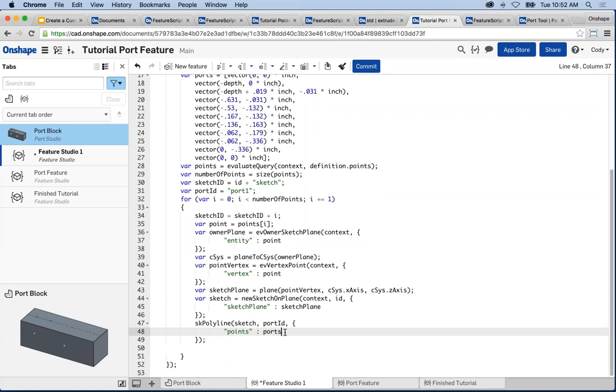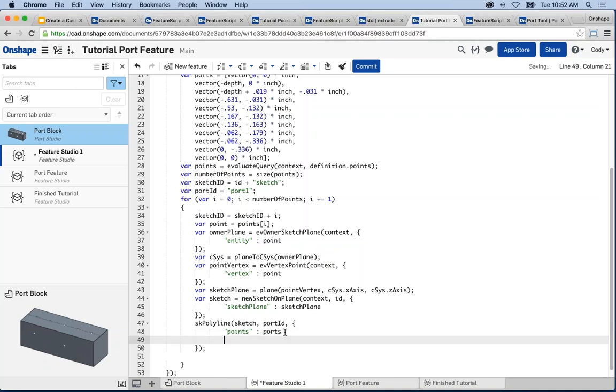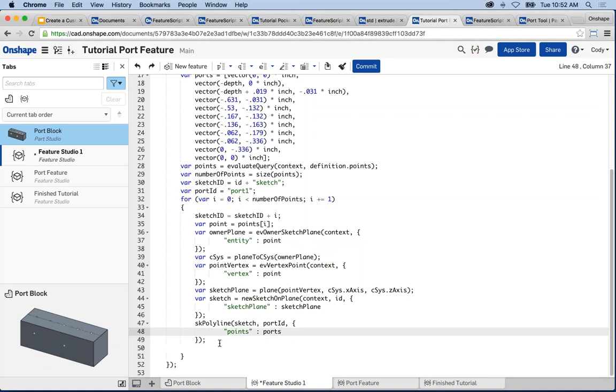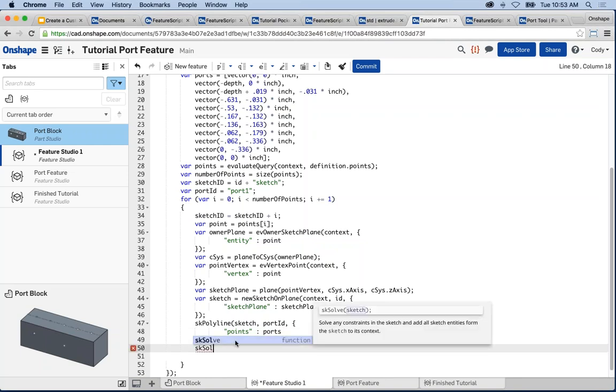the actual revolve. Now, before you finish any sketch, as you're constructing geometry with sketch, make sure when you're done to select SK solve. Okay, SK solve, and then sketch. Okay, that will solve the sketch and make sure that it's visible in the graphics. Okay, real quickly there, jump out. Okay, here we go. SK solve. Okay, so make sure to solve the sketch.